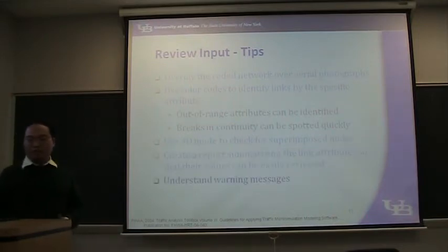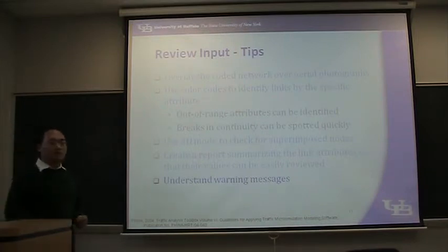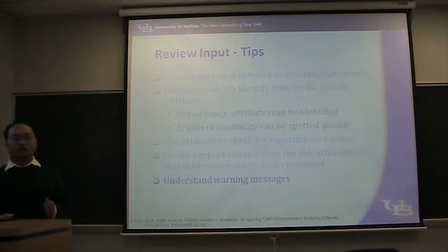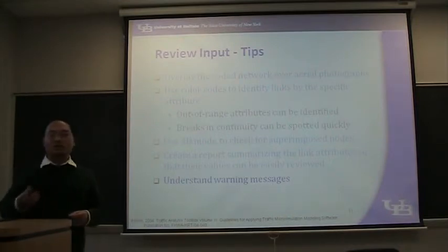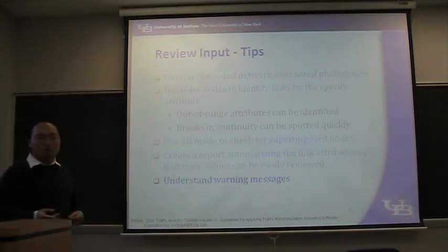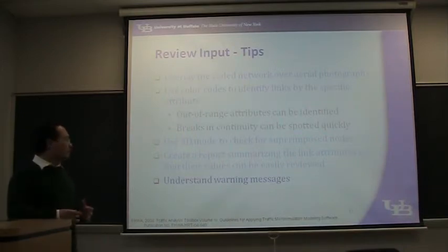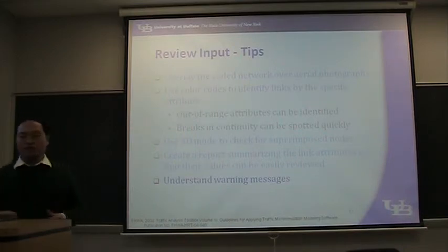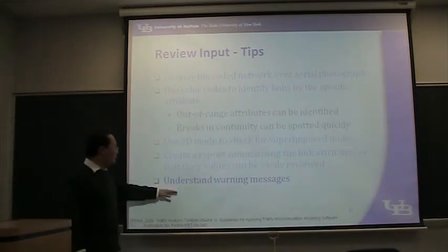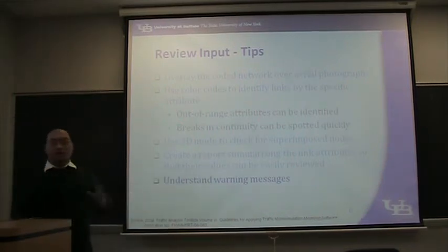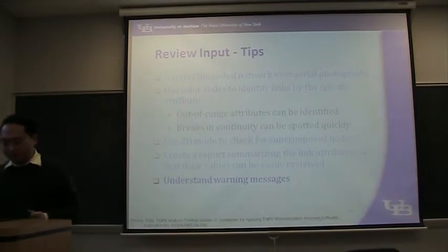The last tip is to understand the warning messages. Warning messages will not affect your result. At least they won't stop you from running your model. But warning messages are always carrying very important information. So at the stage of error checking, before you check your errors, try to understand all the warning messages.